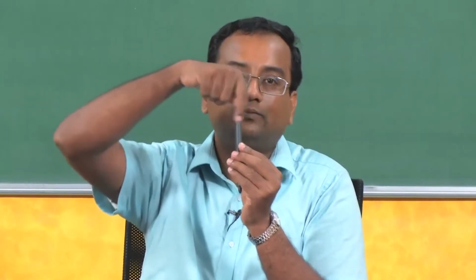The radius of curvature of the wound wire, which is bent around this pen, would be the radius of this pen locally. So, I will use that radius of curvature here to estimate what my bending stresses are directly in that case. So, basically this is E by R.